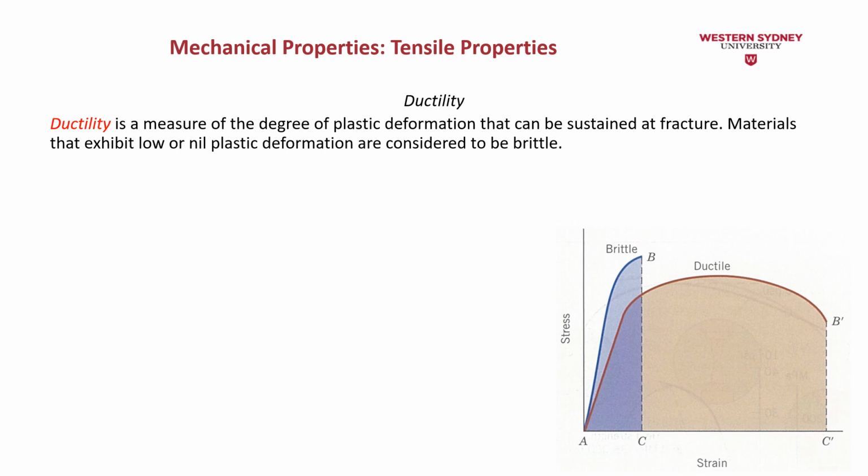Something like some of the metals, like aluminium, if you try to bend it cold, it will simply fracture. So it has good ductility to a certain limit. While steel, you can bend even cold to a very high degree without having a fracture appear on the upper side, because you're going to have compression on one side and tension on the other side.